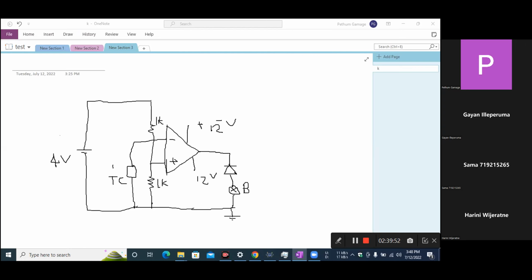The way you have connected it, I think the buzzer sounds only when the output is negative, right? -12. Yes, sir. That's a little bit not the normal method, but what you can do is remove the +12 voltage. You can have 0 and -12 as your op-amp supply. Then what will happen is your op-amp output can go up to 0 volts, not above it because your supply doesn't have it. But it can go below it because your supply has -12. You get what I'm saying?